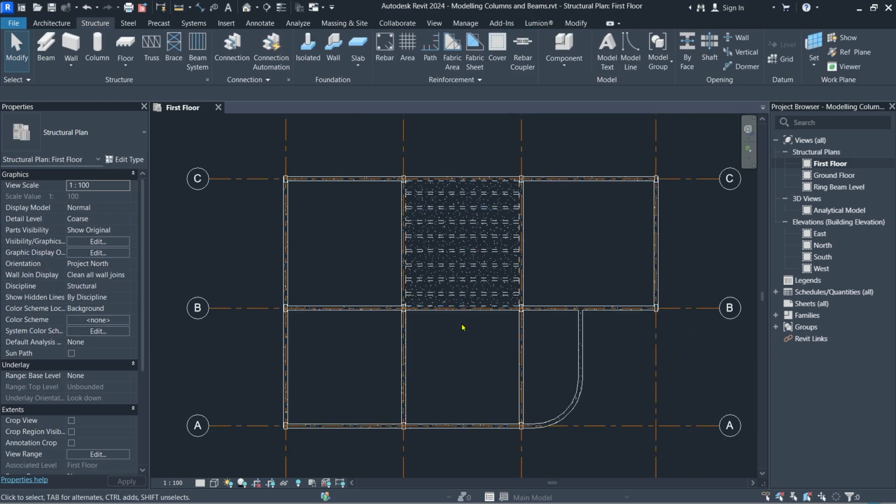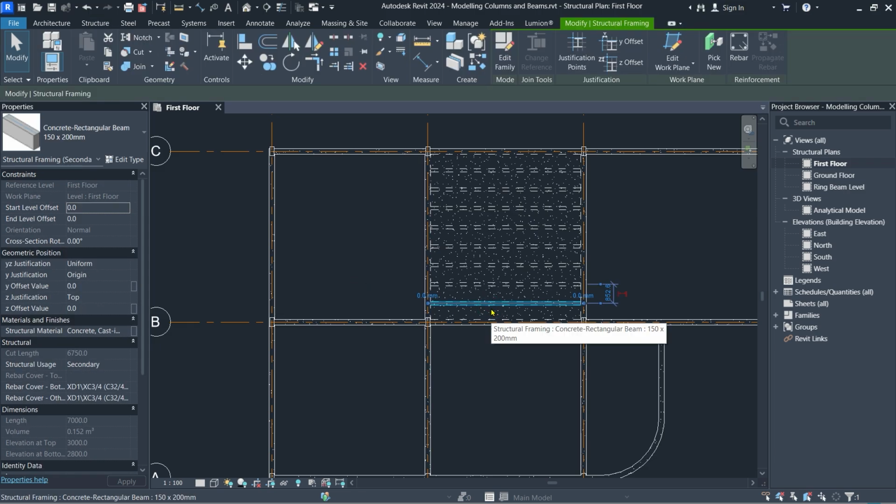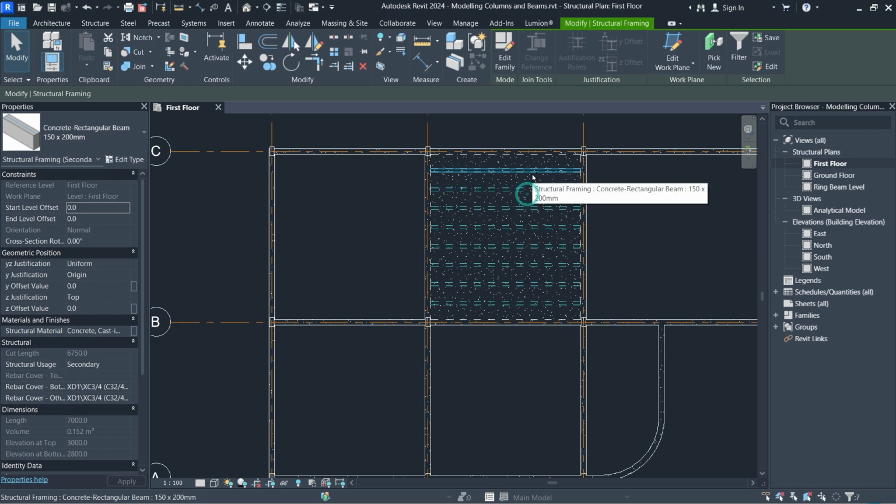So let's say I want to extend this system, this side and this side. It's a simple thing. You can try it out and see. So I'll leave that homework to you. But by now, if you have been following me, you can easily do that. You realize that you can select these one by one by clicking one, then hold down the Ctrl key and click the rest like that before you walk around with them.